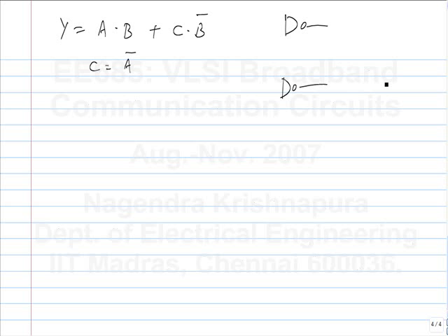So a latch is basically a memory element, and the way you get a memory element is by having positive feedback. This is self-restoring. If you have a 1, that's 0, and then that 0 sustains a 1 and 1 sustains a 0. So as long as the power is applied, the states will be like this, unless you disturb it with some external means.